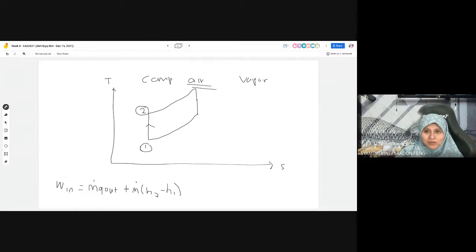Okay, last one for today. Number 5. Okay, this one is refrigerant. Refrigerant R134A is an organic fluid. So it's not water. So obviously you cannot use table A6 or table A13. Water is not the same. Okay, so you have to use another table.